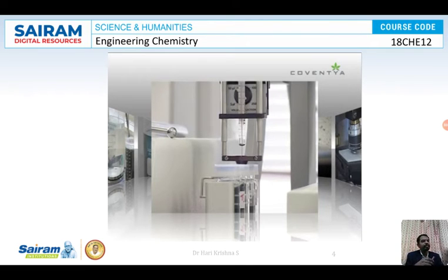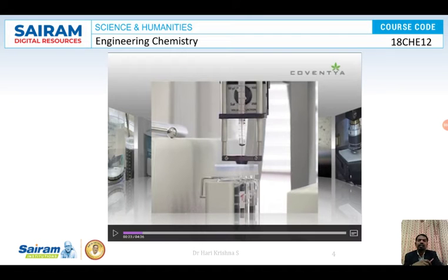This is because the substrate is dipped in a solution and a reducing agent is added. Whereas electroplating is done only for conductors because it's connected to a DC power supply. Electroless plating can be done for anything: plastic, ceramic, glass, any non-conductors or insulators. Let's have a look at how electroless plating is done.